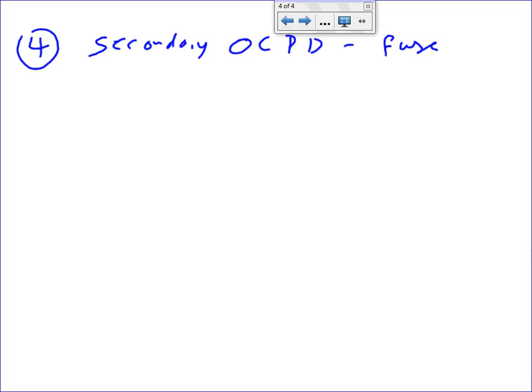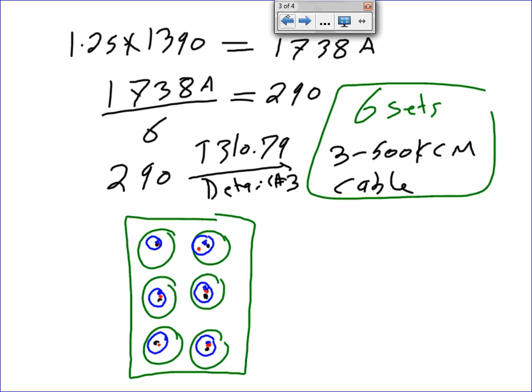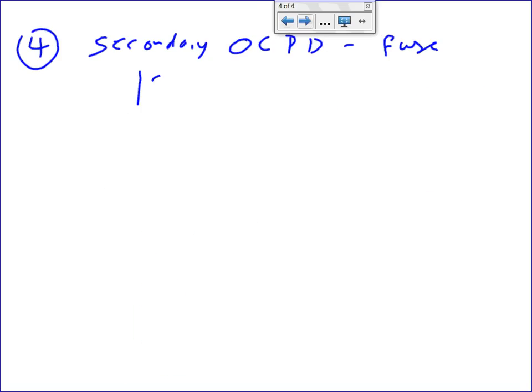Okay, so what did we say the amps on them? Can you just give me the amps again that we found? 1390. So you take the 1390 multiply by, I think 3 again, from table, which table? 450.3(B). It's a fuse. Look at the 250. Okay, for a fuse, 250. Yes. Do they have the note number 1 on it? Yes. Okay, so 2.5.